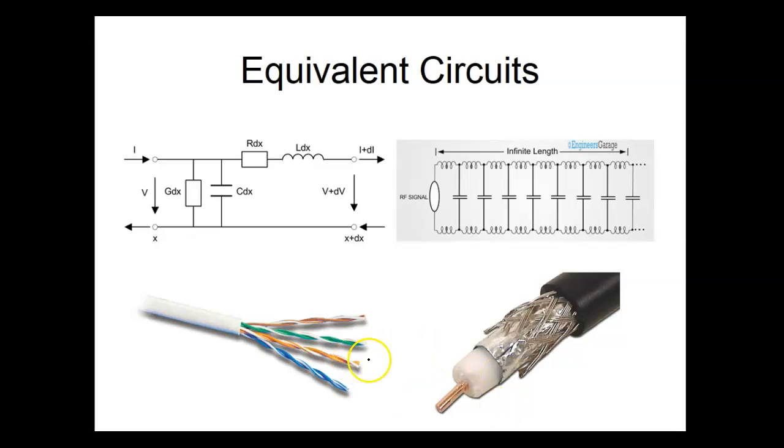Yeah, but when you do these splices, they're precise. You've got to do them right. This is twisted pair, so this sets up inductance and capacitance between these two cables. This is 100 ohms. If you ever did networking, you see people untwist it to make it easier to splice. A quarter inch is the maximum you're supposed to untwist, guys, when you put your connectors on, because if you get it out of that twist too far, you screw up the impedance of your cable.